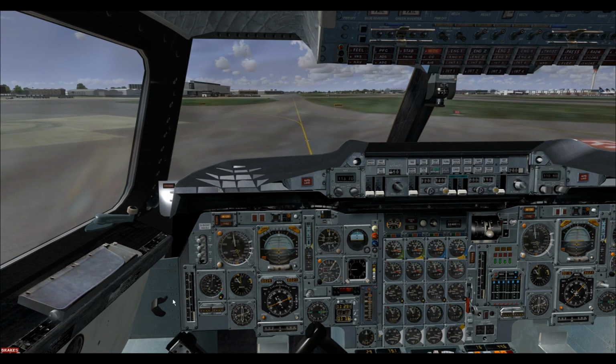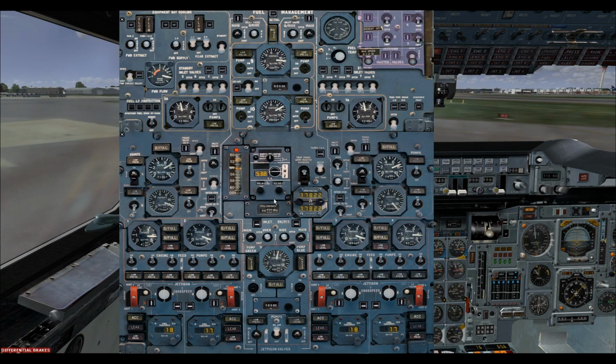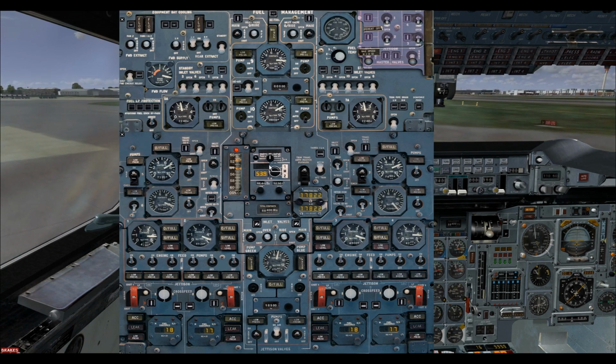You recognize what's happened. You put on the brakes. You go, oh, geez, great. I'm now at 53.9. I'm supposed to be at 53.5. So what do you do? Well, fairly straightforward to fix. You've got to close your main inlets so fuel doesn't go into tanks 5 and 7. It's a bit of a pain, but you're going to have to fix it. So you lower your load limit controller